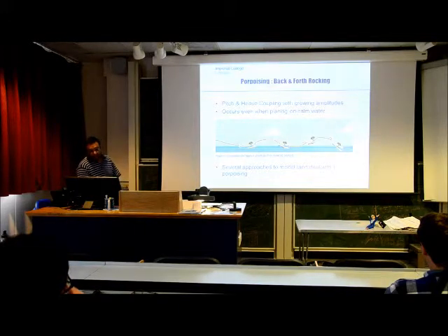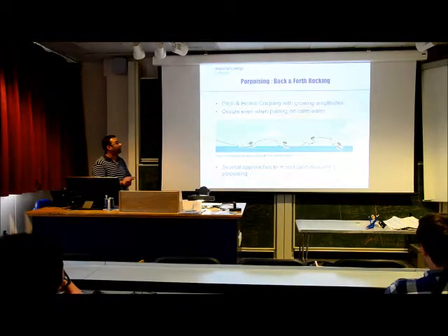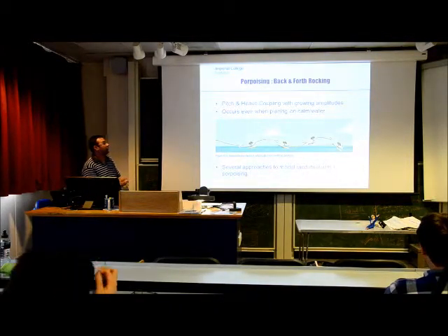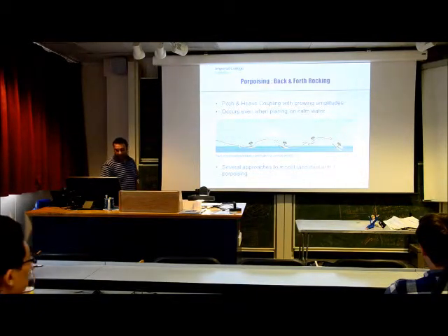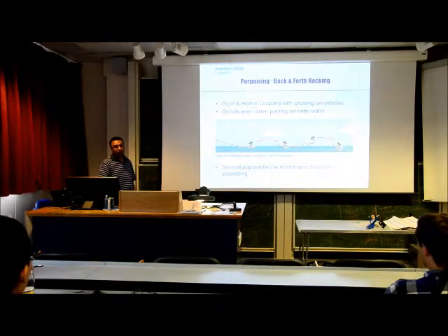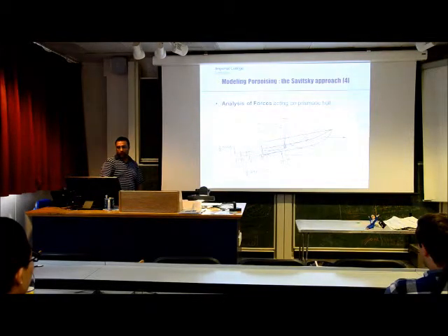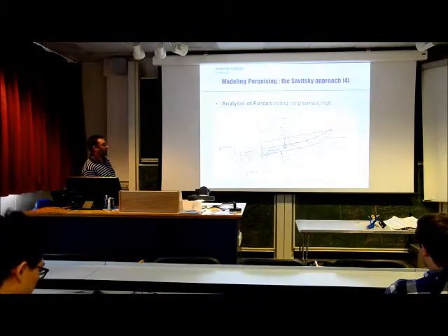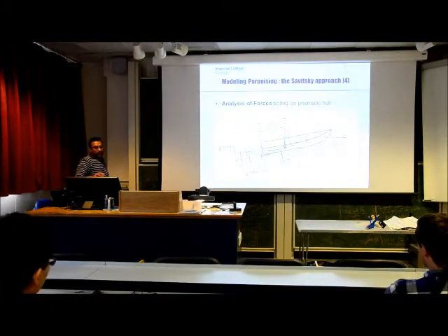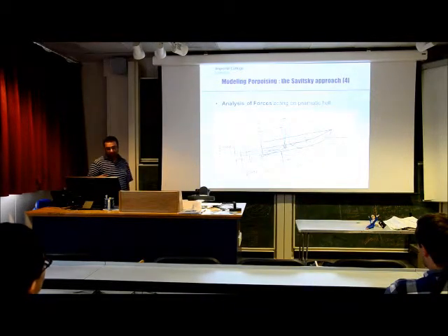As we introduced last week, porpoising is a pitch and heave coupling with growing amplitudes that can lead to several problems with takeoff and landing equally. There are many different ways we've found to model and deal with porpoising. For the forces acting on a prismatic hull, the analysis very often confines the diagram of forces to what's going on at the surface of the hull, instead of accounting for the whole body.